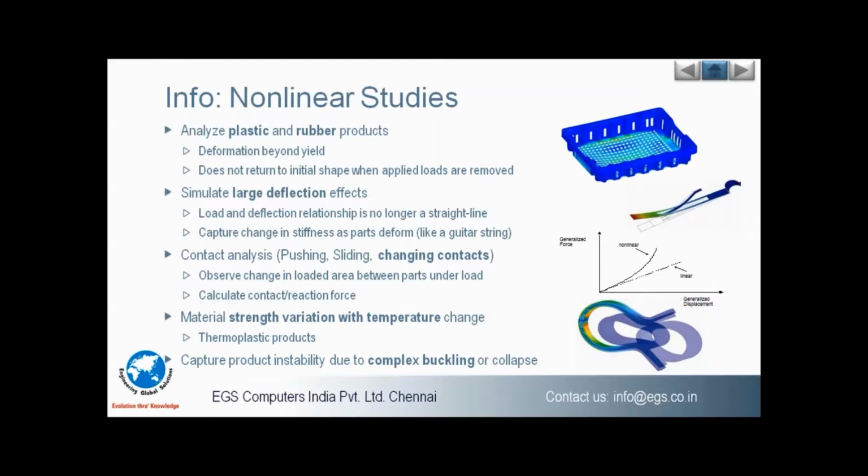Coming to the information on the nonlinear studies, we are going to analyze the plastic parts and the rubber products. If our organization is dealing with plastic components or rubber components, nonlinear analysis is very helpful to study the deformation beyond the yield value. As we have all studied in the mechanical industries, when the loads are being applied, the product is not going to retain its original shape. That means the material has undergone a plastic deformation.